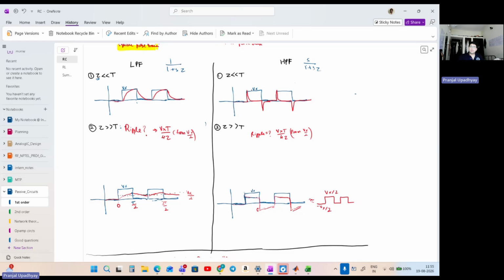Again, we can solve this mathematically also, and the way to go about it mathematically is to just try to solve it for one interval. What you can visualize this problem as is a unit step like this, and another unit step which is shifted by T/2 if this entire interval is T, and then you can just apply superposition, right? You just try to find the response for this, and then the response for this negative unit step. Does this work? Let us quickly talk about this.